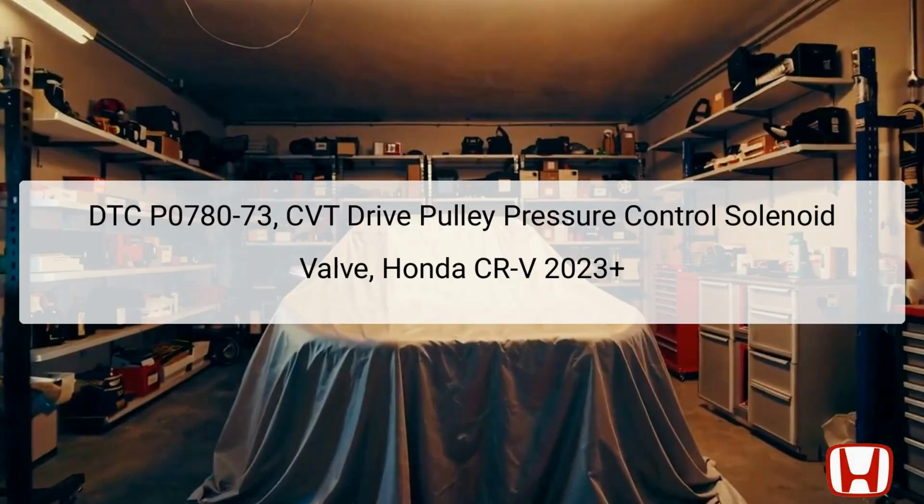The diagnostic trouble code P0780-73 indicates an issue with the CVT drive pulley pressure control solenoid valve. This solenoid valve is crucial for controlling the pressure in the continuously variable transmission, CVT, affecting how power is delivered from the engine to the wheels. Its malfunction can lead to issues with pulley ratios, which may dramatically affect the vehicle's acceleration and overall performance.